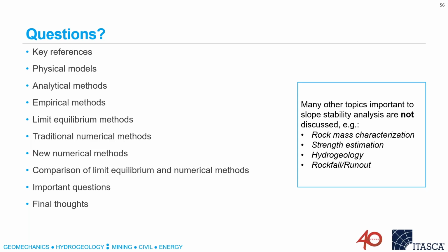Use that particular model where it's appropriate. So soil models for the soil part, and rock models for the rock part. And you can do that with almost any numerical model, whether it's Itasca's or Rocscience or anybody else's. They have a variety of material models, and just use those where they're appropriate.